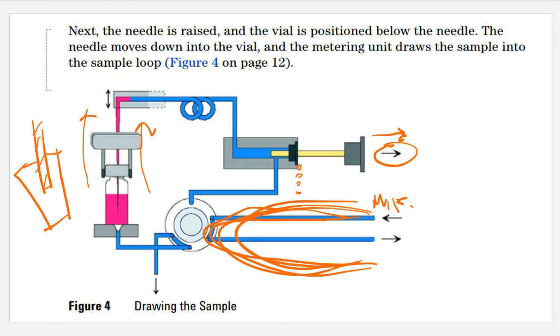Well, just like the LC auto sampler, if you get leaks on this back end from the seals or from damaged pistons, you're not going to be able to get liquid up and out of those sample containers. You got to make sure that those are performing legit. That means replace the seals and replace the pistons if needed. If you see leaks here, you got to do some consumables. You can't just watch the leaks and be like, oh, it'll be okay. It's not going to work.